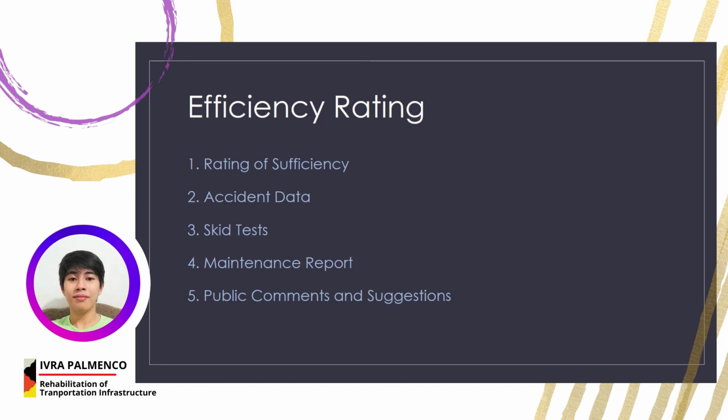The rating of sufficiency is a tool that is used to help determine whether something that is structurally deficient or functionally obsolete should be repaired or just replaced. It considers a number of factors such as cost, reliability, and efficiency, and is ultimately the basis in deciding which projects are either continued or terminated. Next is accident data. Accident data or statistics include a record of road crash statistics and can be used to help identify hazardous driving locations. In doing so, distinction is made between accidents based on accident experiences and accidents based on the specific geographic or physical features of the location.